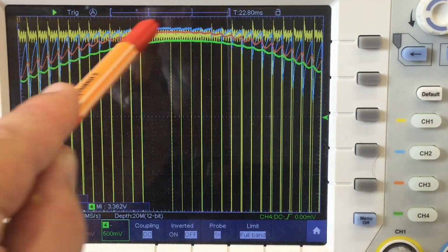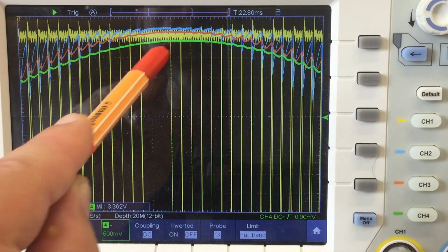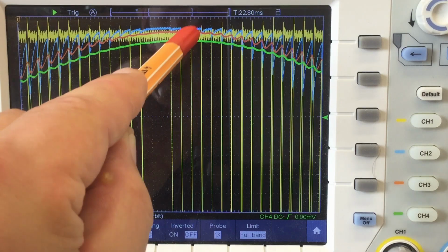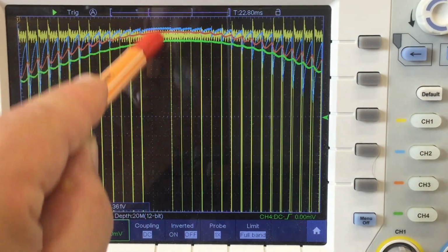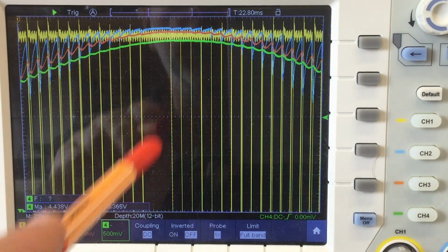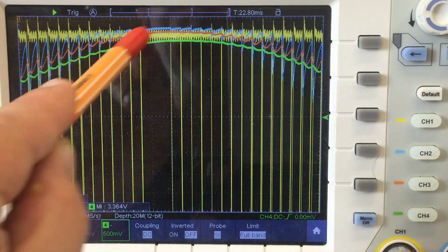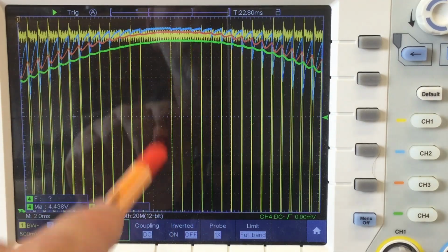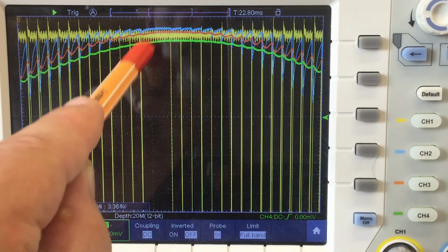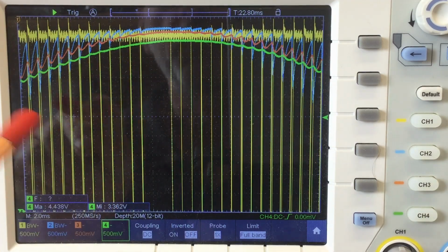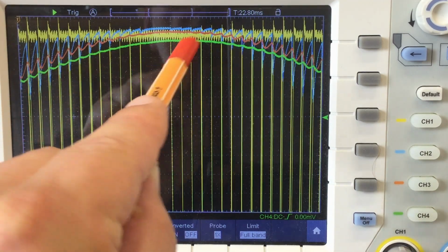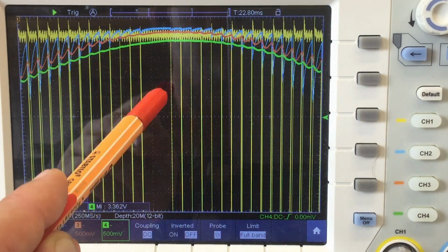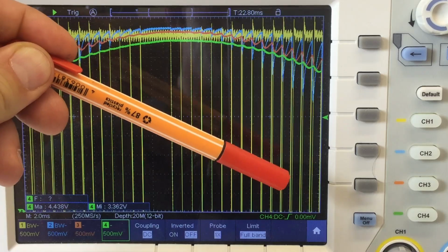So after our first stage here, you see the maximum of the first stage is a wee bit delayed compared to the maximum of our PWM signal. The reddish line, you can clearly see that the maximum comes a few cycles after the maximum of our PWM signal. And the green line, it has a maximum clearly here, where the PWM signal is already ramping down again.